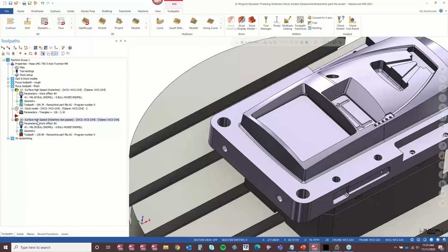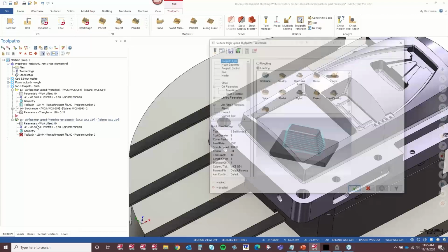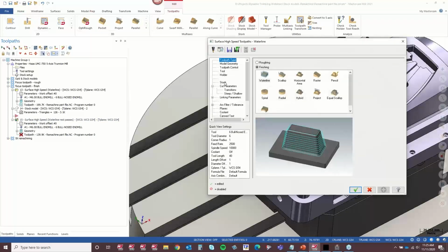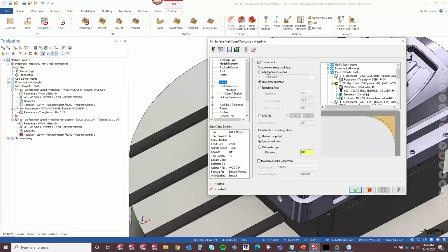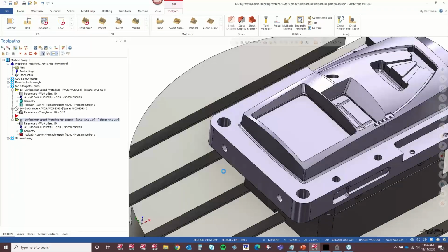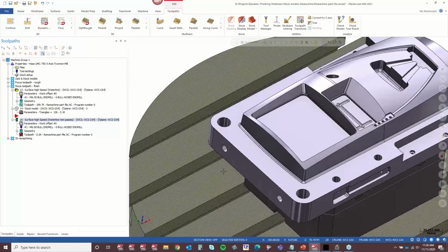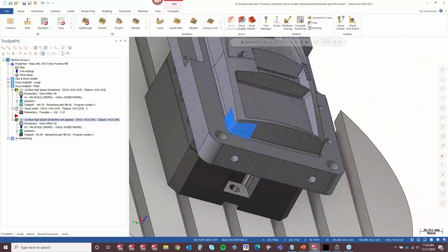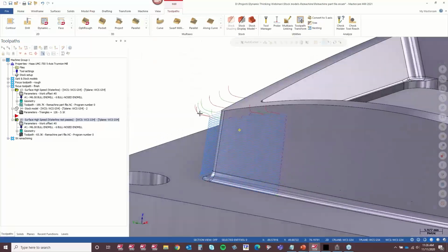So now I can say, all right, well, let's copy this waterline toolpath down, and let's, in our stock tab, finishing operations have stock tabs as well. I can say, okay, let's reference that old stock model. Okay, and that is operation number 14. So I'll scroll down here, op 14. Okay, now I regen this waterline, and it's respecting only that corner area.